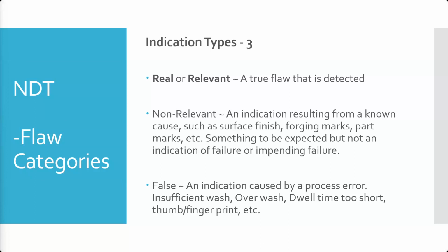And we would compare how long the crack was, say, 1,000 hours later, to how long the crack was 1,000 hours ago. We would also ask, is the crack still less than 2 inches? So if the crack was less than 2 inches and it didn't grow more than somewhere between 1/4 and 1/2 an inch during that time period, GE would say it's okay